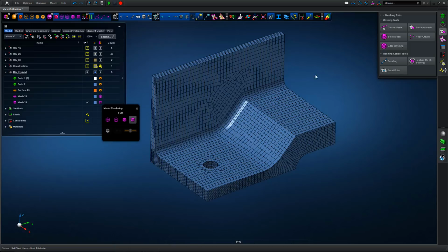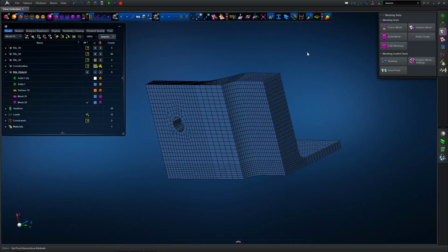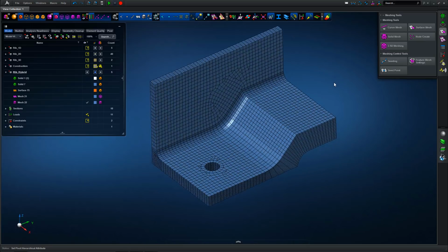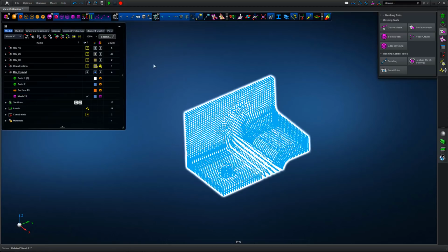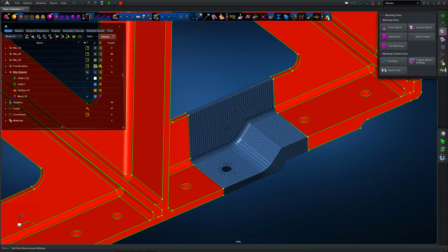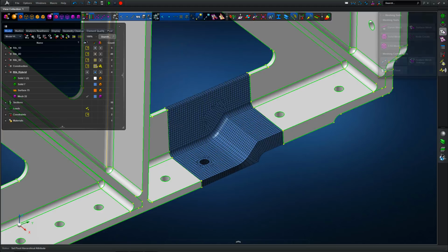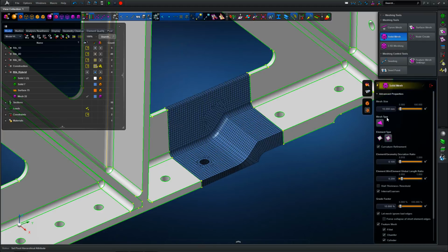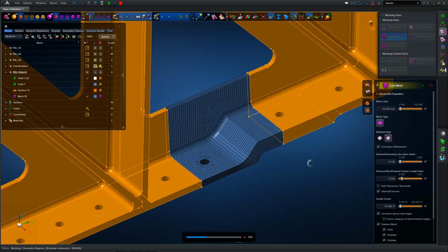So just playing around with some of the display controls, going back into a 3D display, we can see we've got a really nice hex mesh definition, and we'd have a significantly smaller node count to capture that set of features than we would with a tetrahedral model definition. So we've got that region of interest hex meshed. We've now got the portion of solid which we cut out originally, and then we can go back into the original TET meshing algorithm.